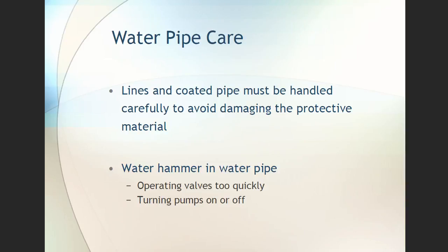Water hammer. You've probably heard it in a house when you turn a faucet on and off, it bangs in the walls. That's water hammer. That's the pressures of coming on and off. And, bottom line, those pipes are not secured correctly, and they certainly need to be. And it's the same thing on a bigger scale in water systems. In water systems, we're more concerned about turning pumps on and off.